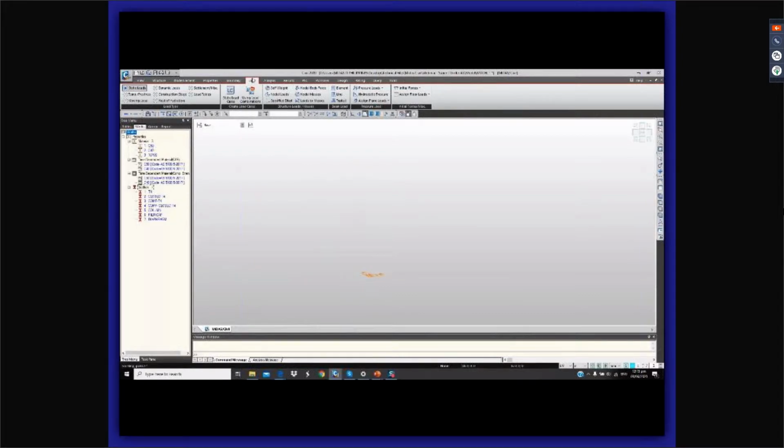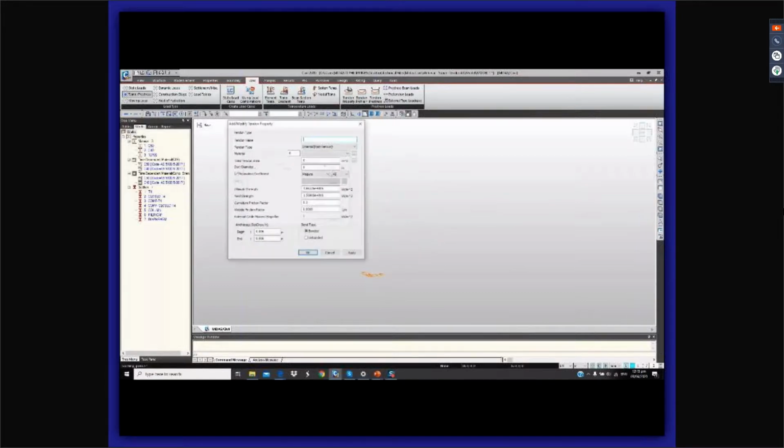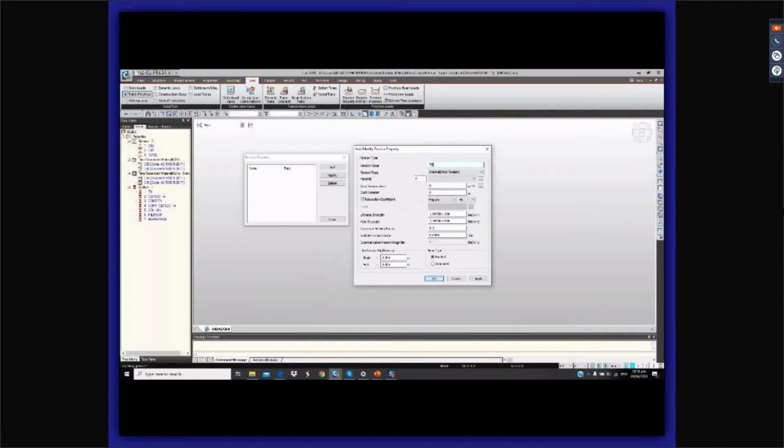It's under the tab, under temp pre-stress loads, then we could define the tendon property here. So tendon property, then add one. Let's make our tendons with one tendon property at first. Then this would be pre-tension. So property girders are pre-stress pre-tension girders. Then for the tendon we'll use 1870 as the tendon. So again, strand of 12.7 mm and the number of strands, let's make it 3. And then strand diameter is automatically computed here.